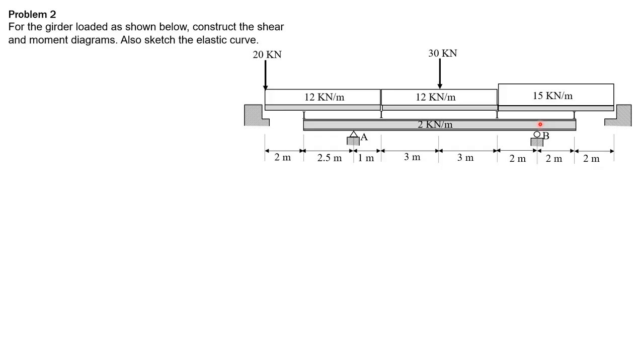So first, let's compute the reactions at these floors here. Then let's transmit these reaction forces to the girder so that we can analyze the girder. So this reaction is 583/7. To get that, you sum up moment about this point here, panel point.